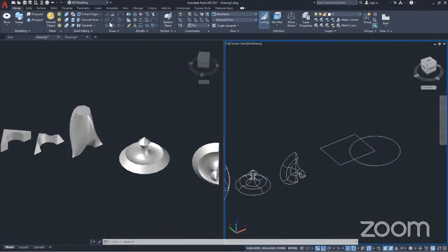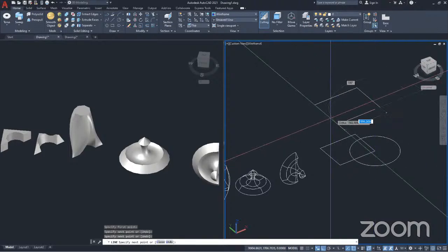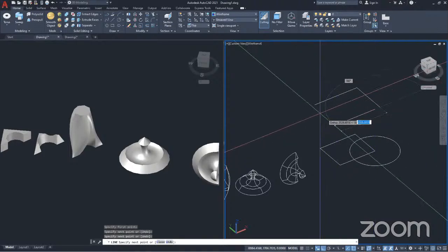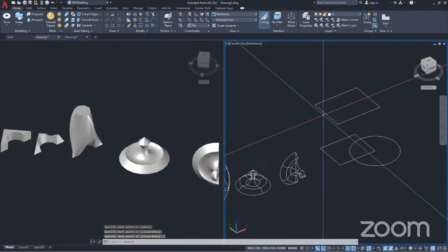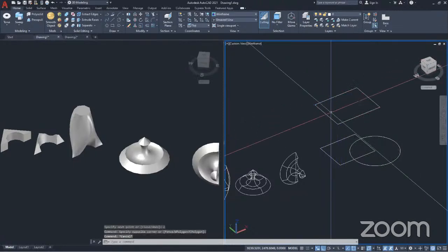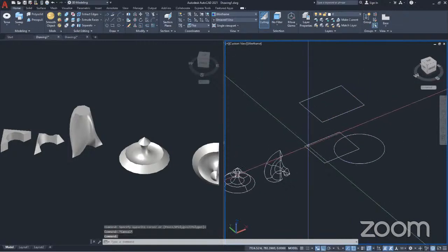Now, see this. If I use a line to construct a box, and use close, you see, of course, you know that with lines, all the sides are segregated, like we all know. But a polyline, in this case, you see, they are all joined together.